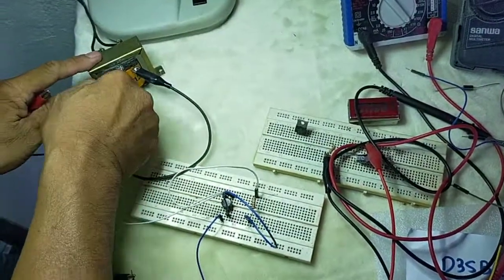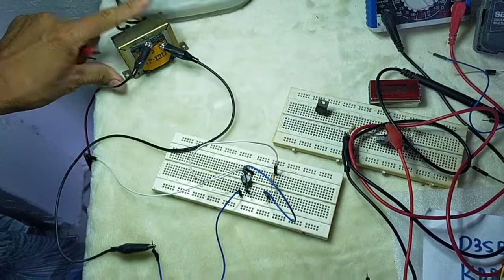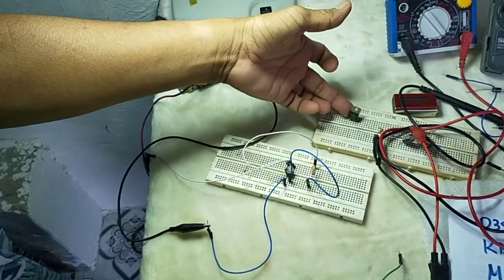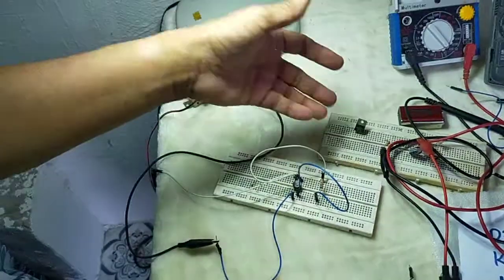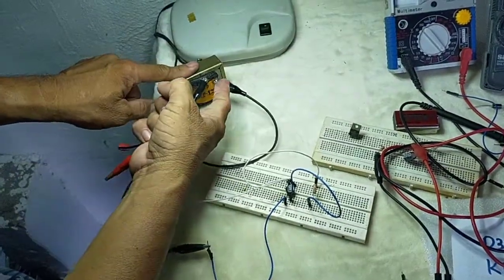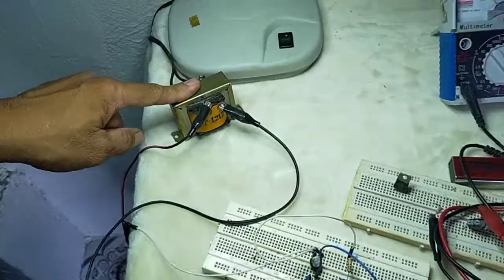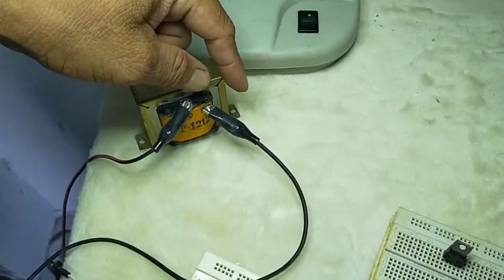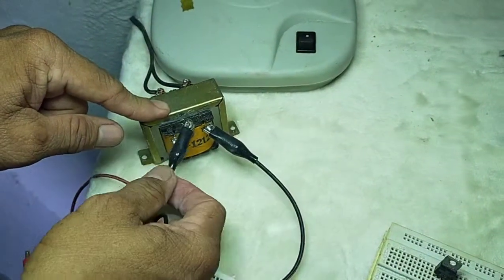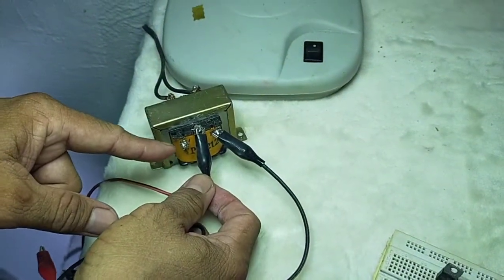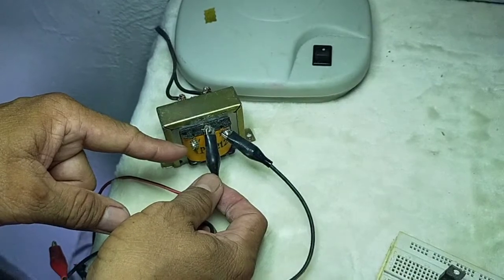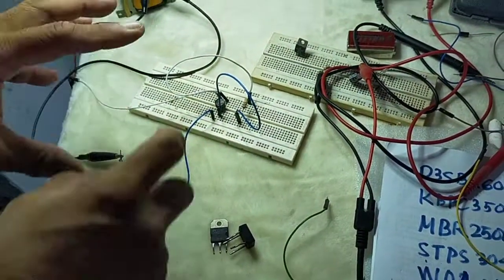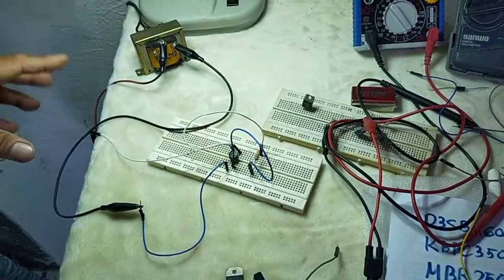By the way, there's a difference between full wave rectifier, which is center tap type, for the dual rectifier. Because for the dual rectifier, we have to use the 3 terminals. But for the bridge type, we will only use 2 terminals. That is 12-0. No? Leaving this terminal not connected. Okay. That is for the bridge type. That is the 2 differences.